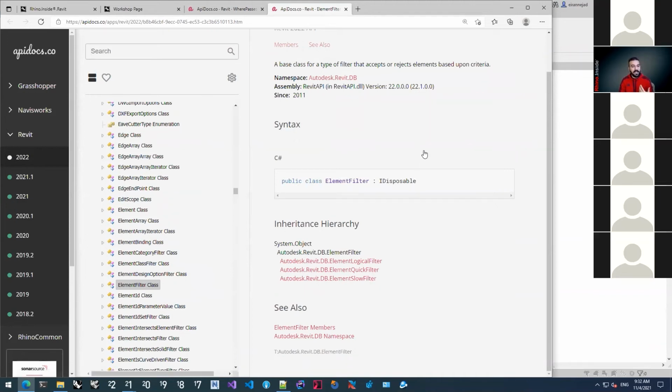One of the examples is that if you try to find all the dimensions on all the sheets in your Revit model, this is going to be very slow, because every time you want to iterate over a sheet, Revit in the backend has to generate the contents for that sheet and try to get that information for you. So just know, sometimes there's no way around it. For example, if you want to see if a view is referenced on any sheets, you kind of have to go through every sheet and see if it's referenced or not. Sometimes there are other ways around this to check it, but sometimes there isn't. And so you have to be aware that sometimes this filtering will take a little bit more time.